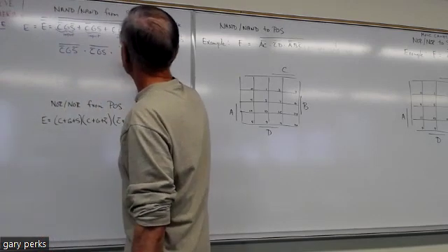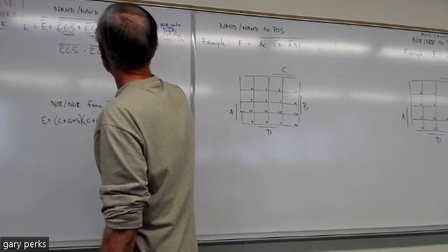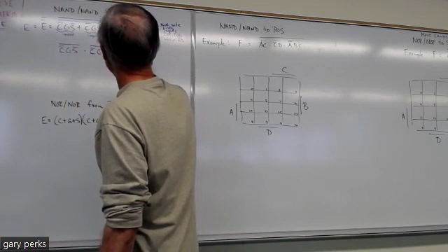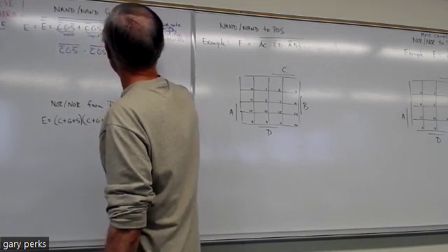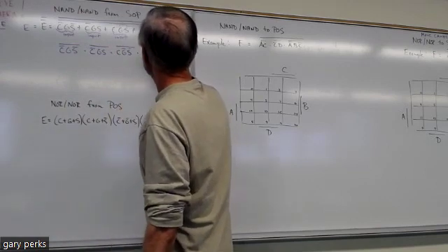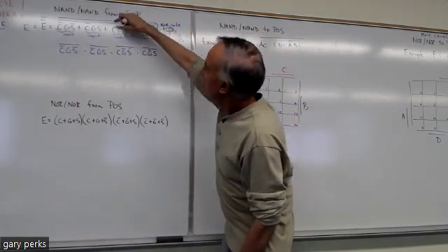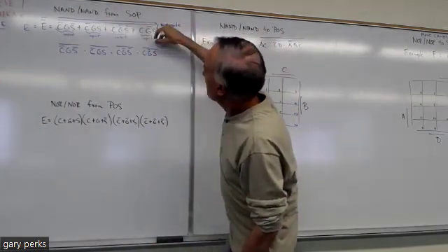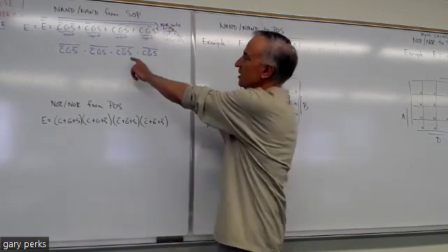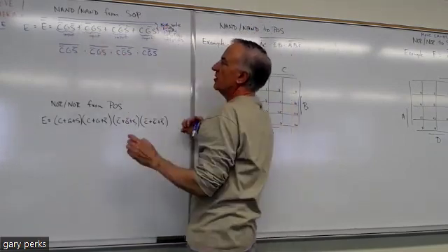We're gonna AND it with, if I make a mistake, please correct me, C, not G, not F, the whole thing inverted. Then we're gonna AND it with C, not G, F, the whole thing inverted. So that's just the bar with everything below it, being a NOR gate, equal to the inputs inverted all ANDed together.